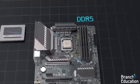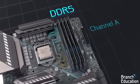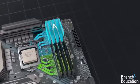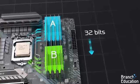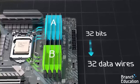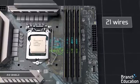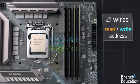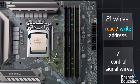For DDR5, each memory channel is divided into 2 parts, Channel A and Channel B. These 2 memory channels, A and B, independently transfer 32 bits at a time using 32 data wires. Using 21 additional wires, each memory channel carries an address specifying where to read or write data, and using 7 control signal wires, commands are relayed.